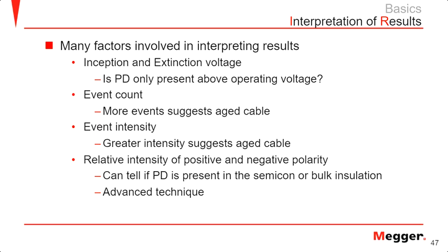Obviously, when you start doing a lot of partial discharge testing, then you would get that experience that, hey, I'm seeing this kind of pattern and this kind of correlates to my semiconductor or bulk insulation rather than a splice.